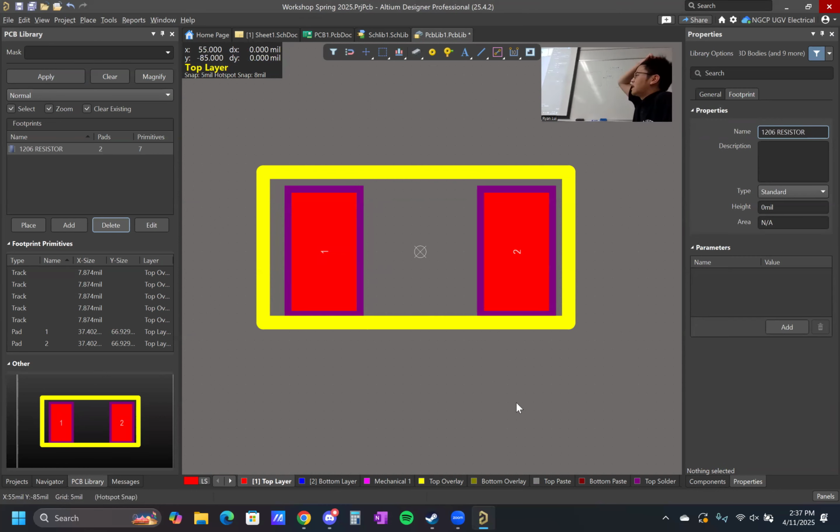That's really handy because that will match with our schematic symbols. And then the yellow line, that is what we earlier called the silk screen. It's the outer ink layer that's not conductive at all. It's just there to help us lay out, or know where each component goes. So once we're done, we can hit Control S to save, and we have our footprint.